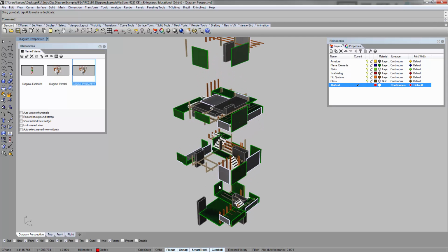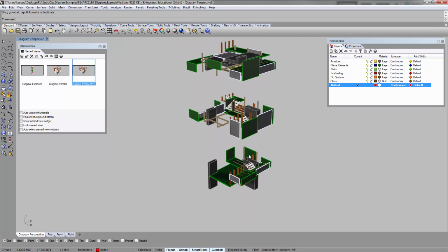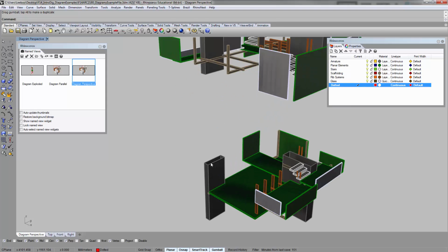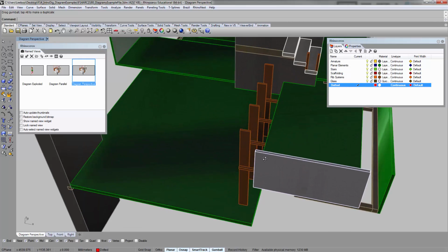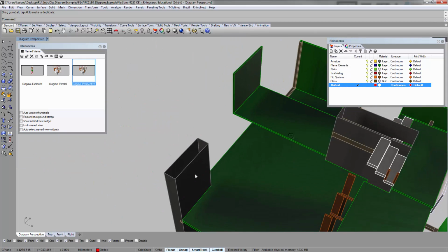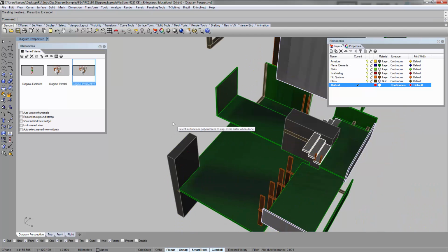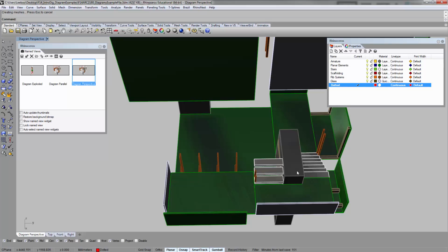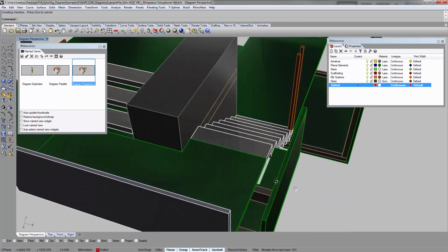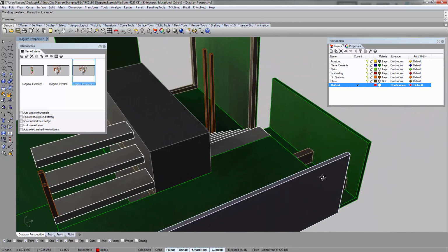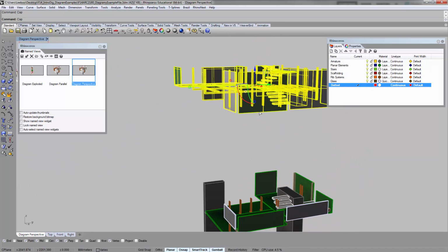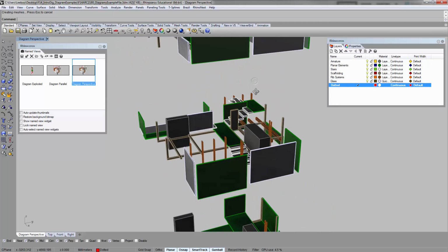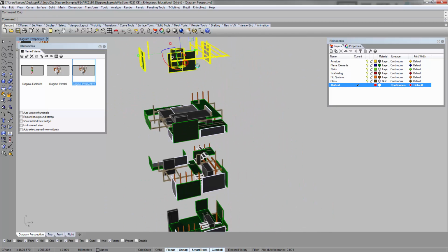Okay, so now you have the sort of separated plan cut. Obviously, where the cut happens depends on you. Same thing, right, because the split command doesn't self-heal, so you will actually have to cap these. And when you actually run it on a group, you'll see that it basically does everything automatically. So select it, cap. It tries to do everything that it can, and so just go through and cap all this.